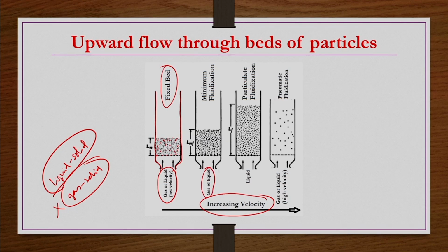When you gradually increase the velocity of the fluidizing medium, the drag force on the particles is balanced by the buoyant weight of the particles, and then once this point is reached, because we are increasing the velocity, that means you are increasing the force of the fluid that is entering into the bed.